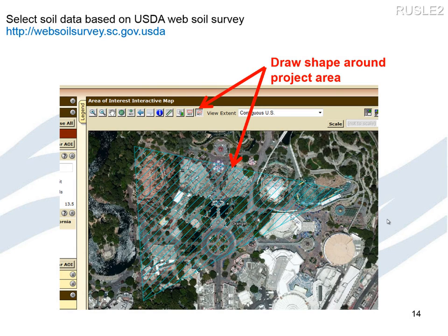These top two buttons, you'll see that the arrow is pointing to one of the AOI buttons there, but essentially it's asking you to define your area of interest. In this case, in Orange County, we've traced out this triangle that gets at what this area of interest is. So that's the first step, defining what your area of interest is. And there's actually a sort of cutoff. You can't have too large an area, otherwise it's going to give you an error message saying you've selected too large an area, and I think it's about 10,000 acres or something like that. It might be an iterative thing where you might go too big the first time, but you have to scale it down to an appropriate size. But this is our particular area of interest, just for example.